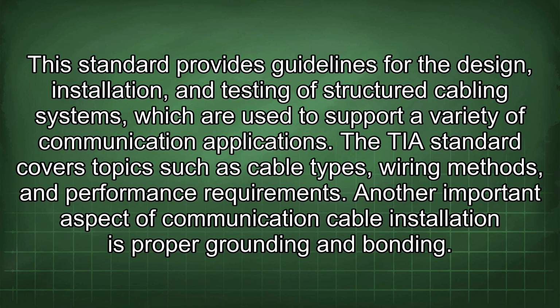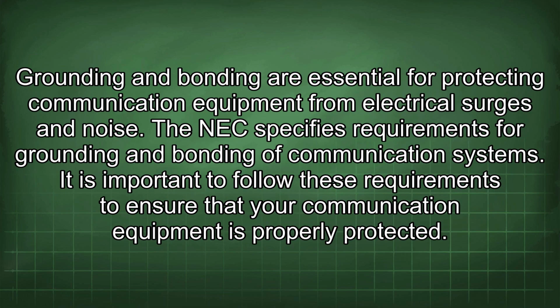Another important aspect of communication cable installation is proper grounding and bonding. Grounding and bonding are essential for protecting communication equipment from electrical surges and noise. The NEC specifies requirements for grounding and bonding of communication systems. It is important to follow these requirements to ensure that your communication equipment is properly protected.